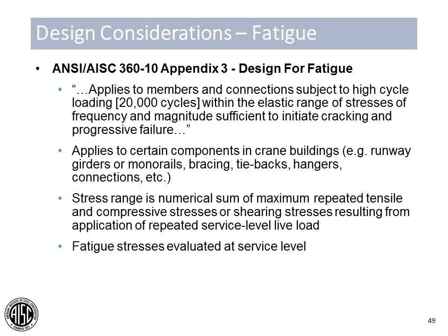This applies to certain components within crane buildings, not just your runway members or monorails, but also bracing, tiebacks, hangers, connections, etc. This is not only a consideration for the runway members themselves. And a note: the stress range is not the maximum tensile or maximum compressive stress that any point in a system is subjected to.